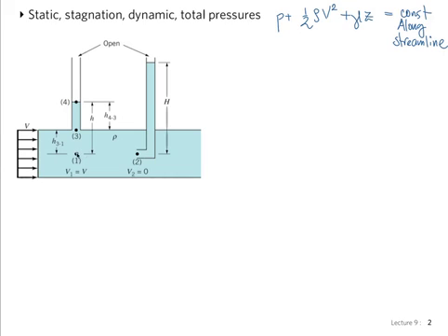We looked at the pressure at point 1, and using our manometer analysis that we've done before, we obtained that P1 was simply equal to gamma H. And that's no surprise there. So the pressure at 1 is simply the hydrostatic pressure there. From this equation, gamma z is basically hydrostatic pressure, right?